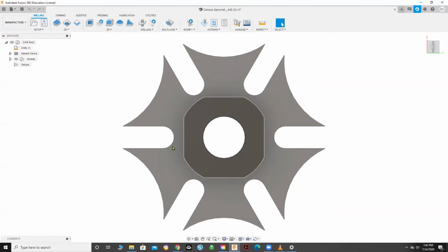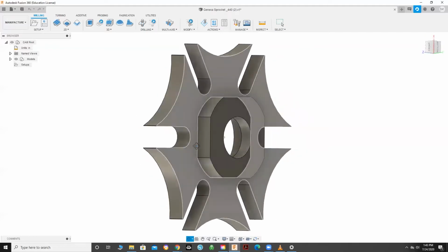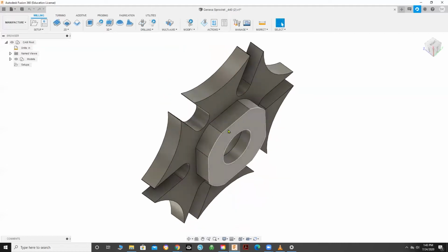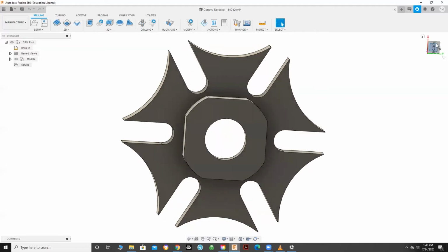Before manufacturing, it is important to have an understanding of how the part will be made. There are limitations to design concepts that are based on cost, expertise, and shop capabilities. These need to be taken into consideration during the design phase. For instance, we designed this part originally to have a round feature at the bottom of the model. It may have been possible to create a jig in order to hold this round feature in place for the second operation. But because that feature was non-critical, it would be cost-effective to flatten the sides to allow this feature to be easily fixed in a vise.